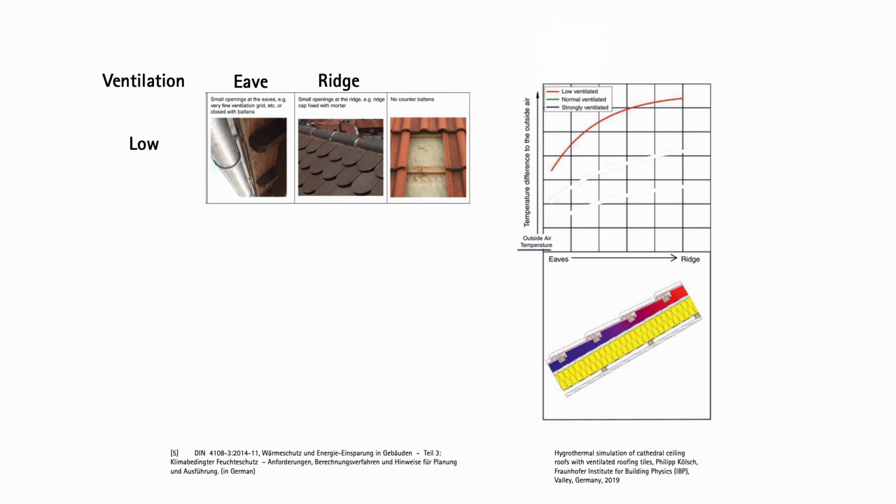So we're measuring the benefit in terms of the temperature difference between the ambient air and the conditions experienced by the roof. And the lower that temperature difference, the better. So we want the air underneath our tiles or the roof cladding to be as close as possible to the ambient temperature. And that's going to avoid getting that really, really hot condition in the summertime, and it's going to avoid getting the sub-zero conditions where we get night sky radiation.